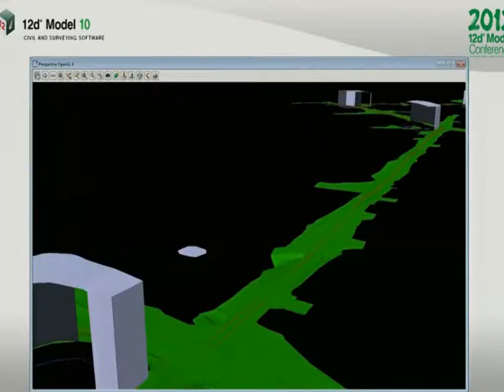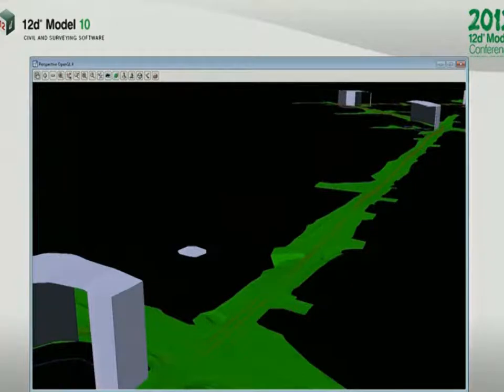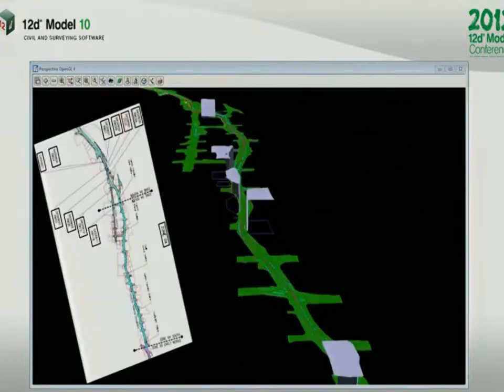Here's another screenshot to show you a bit close up. Besides modeling the sight stopping distance, this macro also allows us to check the signal sighting along the route. This is actually quite useful for the signal designer. As Dylan already mentioned, we have nearly 60 intersections and at least 2 sets of traffic signals along each intersection. So we have to make sure that the tram driver can actually see the signals in order to stop.